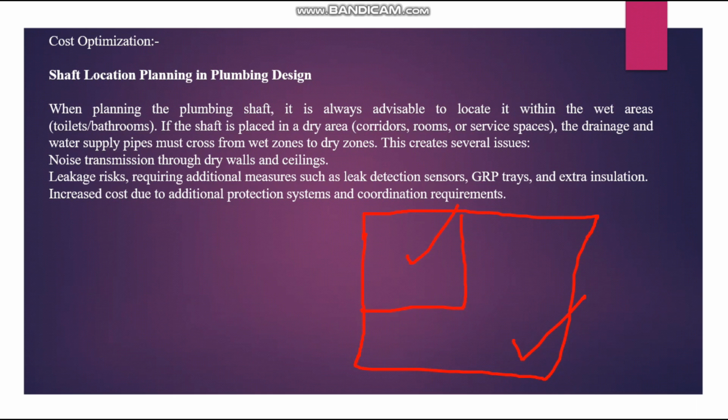The soil stack planning is one of the important things in the design, because sometimes by mistake, for example, this is your entrance, you have the kitchen here, you have one door to the entrance here, we have the bedroom here, so this is the bedroom entrance, and you have the hall here. Sometimes the soil stack location is planned in another location by mistake. For example, it will be this area, near the living room. So you have to direct the pipeline like this, all the way to here, or you have to direct it through like this.